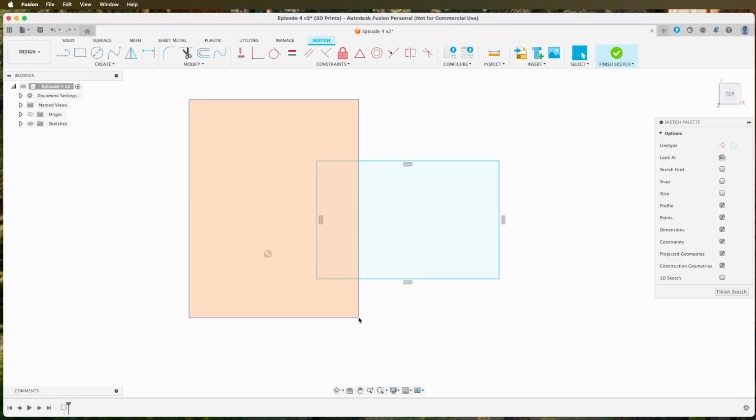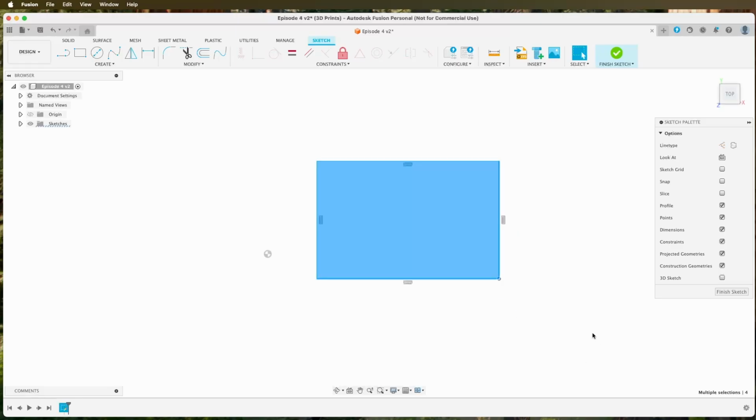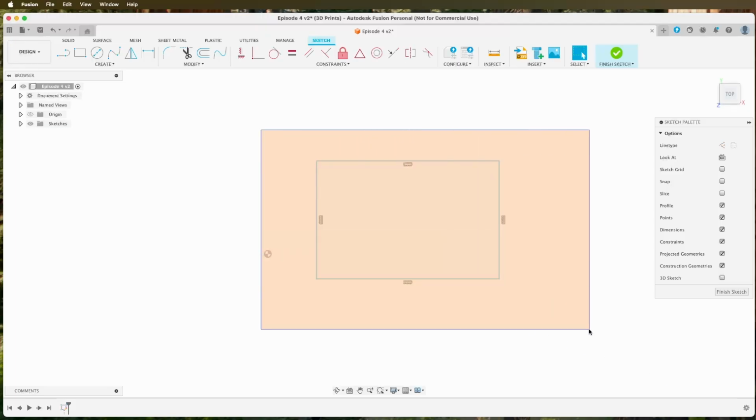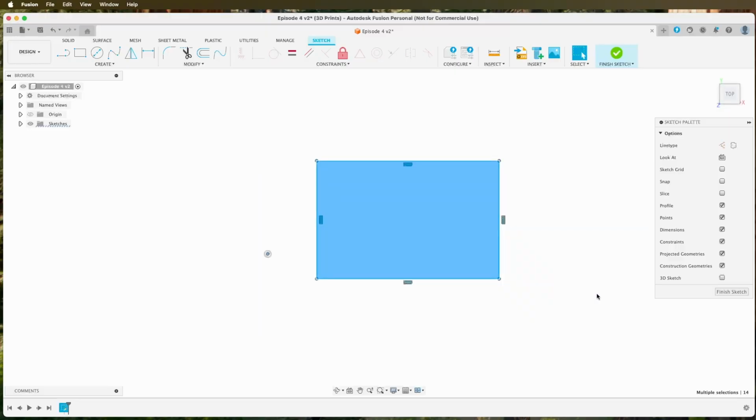So the left to right can be useful when you want to select just a line, and it doesn't matter if you cover the others, because they won't be selected as long as the full line is within your range. With the other one, if you want to make the whole selection, you just drag and cover a portion of the object, and it will select. For example, with left to right, if I do it this way, only the bottom line has been selected. However, if I cover the whole object, it gets selected. So let's see what the move tool does.